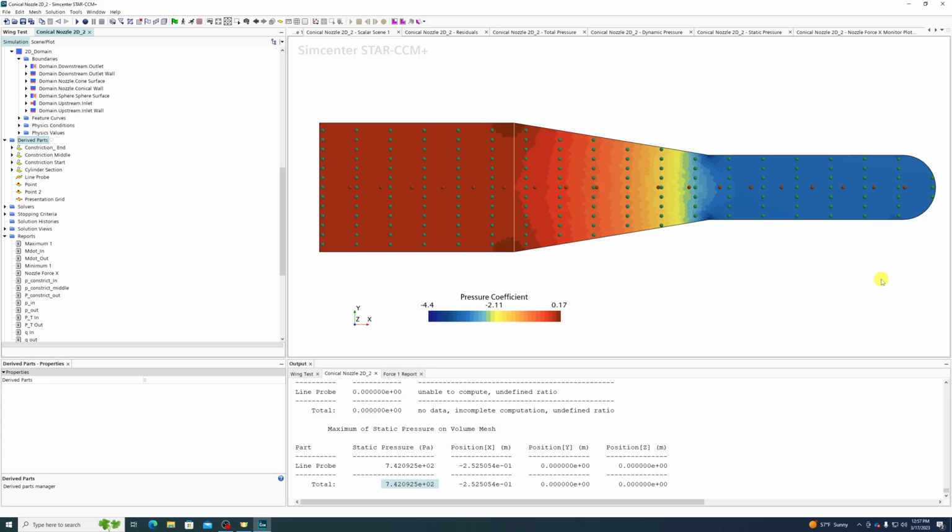So what these probes let you do is measure pressure in specific locations. If you measure the pressure in your simulation at the exact same point where you measure your pressure in your experiment, you can directly compare them and do what's called a model correlation. That is, they're not going to agree exactly, but you can tune your model so that it agrees with the experiment. So if you wanted to simulate something else similar, you have greater confidence that it works, because you know, hey, I maybe didn't do an experiment on this exact thing, but we simulated something similar, we did an experiment on something similar, and we got the two to agree for that. So if we simulate this other thing that's close, it should also agree. That's kind of what's called a model correlation effort. If you correlate one model, you have greater confidence in all the others.